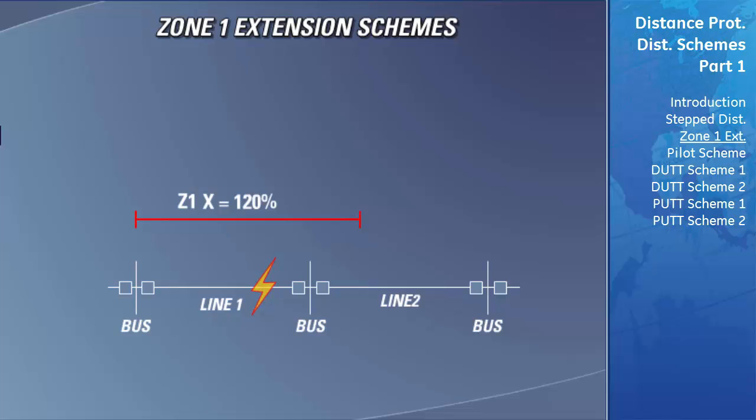When the breaker is opened and the fault is cleared, the relay will automatically reclose the breaker and re-energize the transmission line. With the line reclosed, the D60 will use the standard Zone 1 characteristic and underreach to only protect an area within its own transmission line.